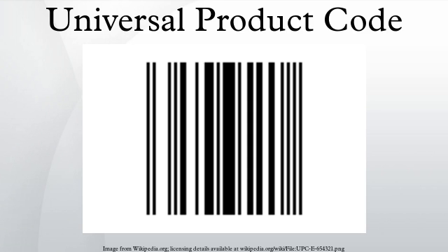The UPC's left side digits have odd parity, which means the total width of the black bars is an odd number of modules. The right-hand side digits have even parity. Consequently, a UPC scanner can determine whether it is scanning a symbol from left to right or from right to left. After seeing a start or end pattern, the scanner will first see odd parity digits if scanning left to right or even parity digits if scanning right to left.